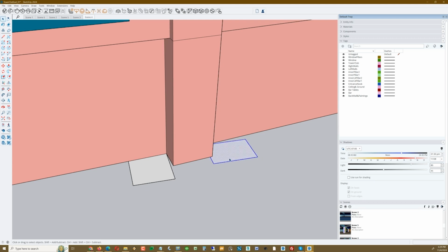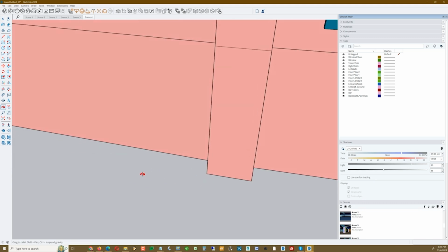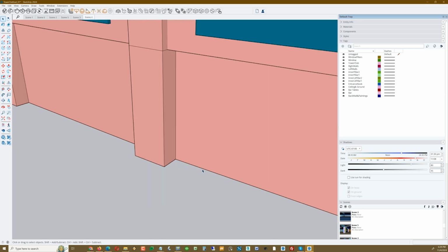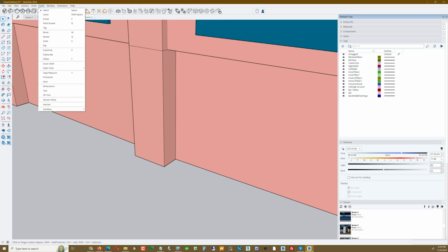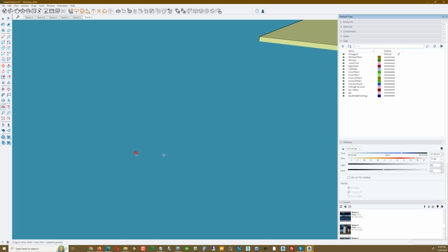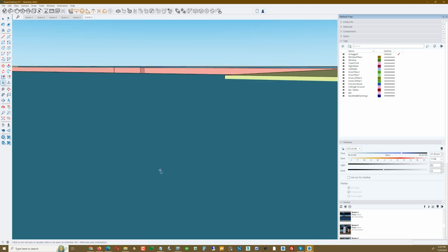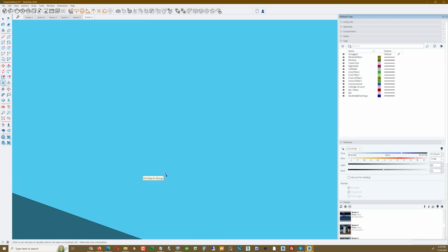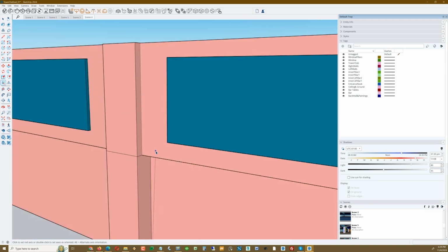I'm going to delete those, come back here, and this time we'll go ahead and build an axis that lets us align along that wall. So if we're going to copy something or build something, it'll already be pre-aligned. So that option is up here under Tools, Axes, and it's just looking, as you can see, for red, green, and blue. So X, Y, Z. We can come along the, let me get back to where I was there. There we go.